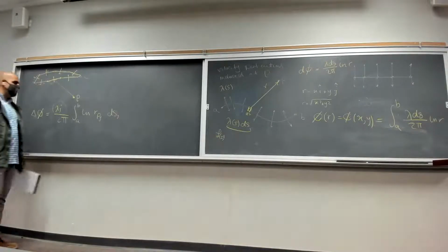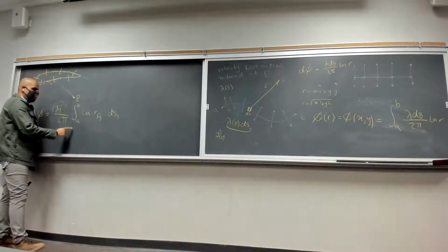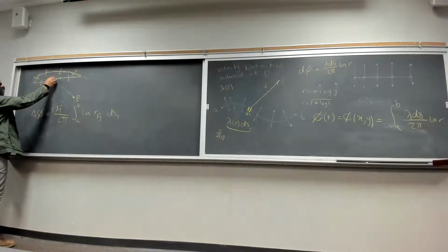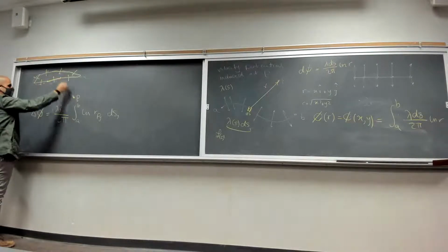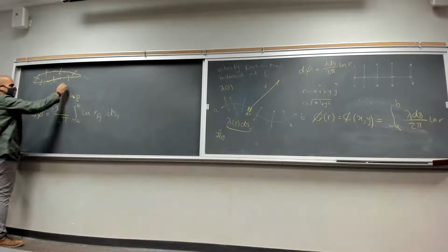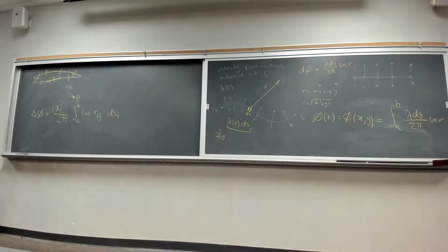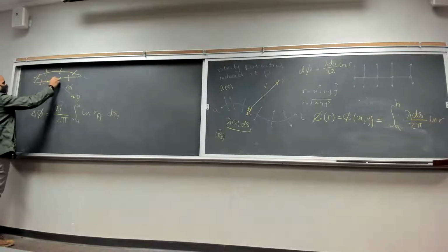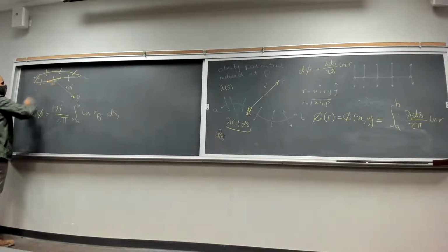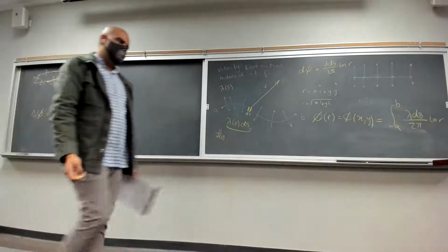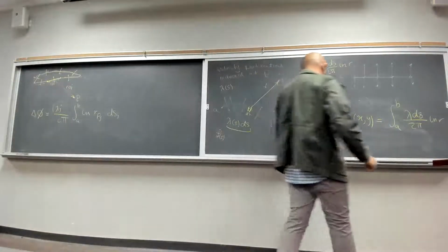And then for the rest of it, we are taking the integral of natural log of r pj, which is the distance between this panel and this point. This is r of pj, multiplied by ds of this panel, this ds, which is a function of x and y in Cartesian coordinate systems, of course.